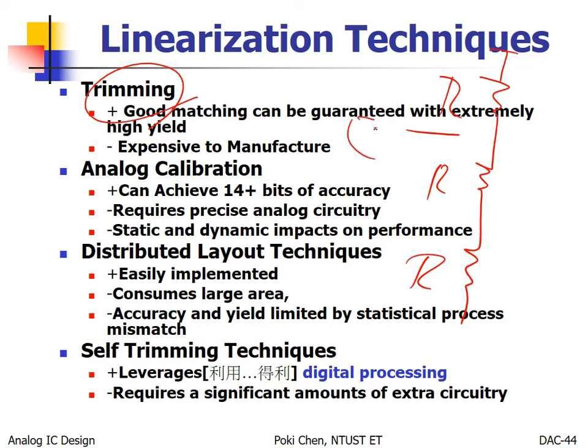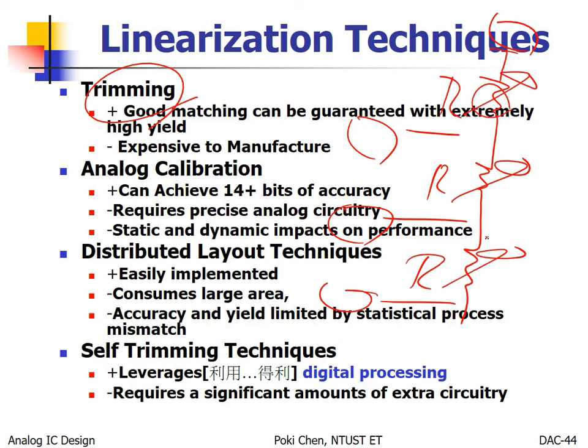You need some kind of test pad or probing pad to measure the resistance and then think, oh, too much or too small. So it means all of them in theory need to be variable. After fabrication, you measure it, then you can fine-tune the resistance.